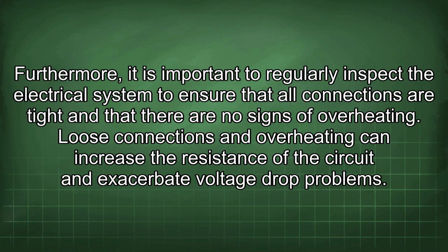Furthermore, it is important to regularly inspect the electrical system to ensure that all connections are tight and that there are no signs of overheating. Loose connections and overheating can increase the resistance of the circuit and exacerbate voltage drop problems.